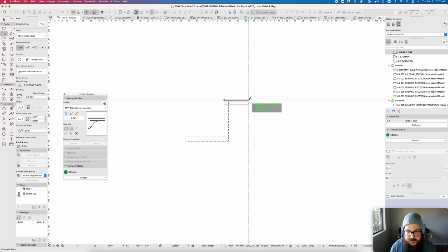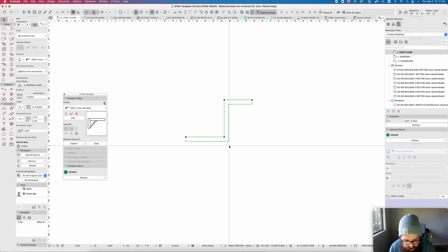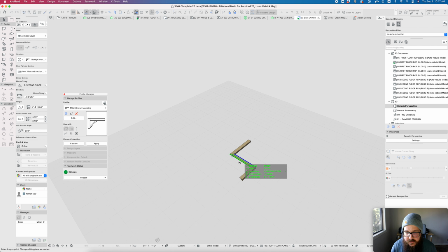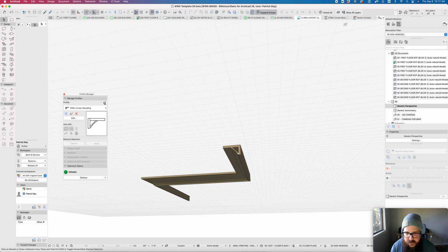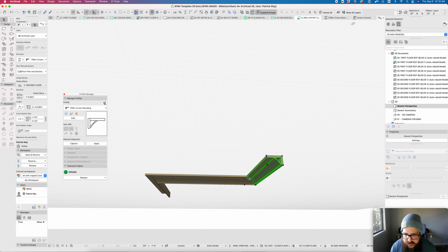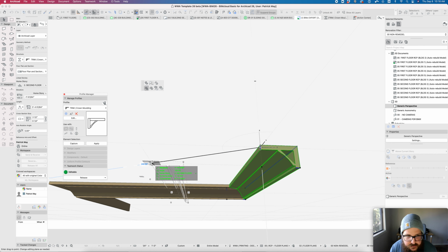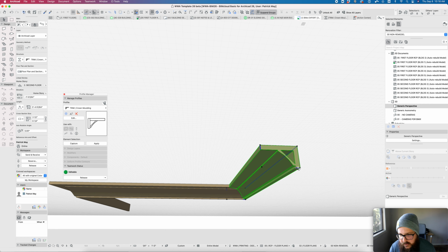Let's just show as an inside corner as well how that all shows in 3D. So we get that profile appearance applied to the beams. And you can see I get that nice 45-degree miter. I also get these extra blue elements, so that gives me a pet palette option for stretching this thing out or back in here as well. Those are those modifiers that we created.